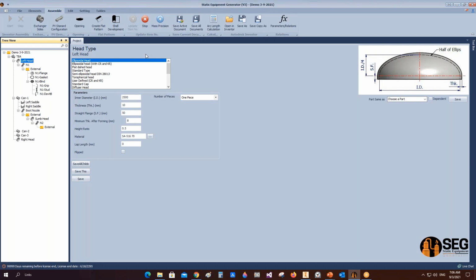So by clicking on update item number, we will reflect this calculated item number to each element created in Autodesk Inventor. This step is very important before starting the drawing, because if you would like to add a balloon to elements, this balloon includes the item number in the bill of material.